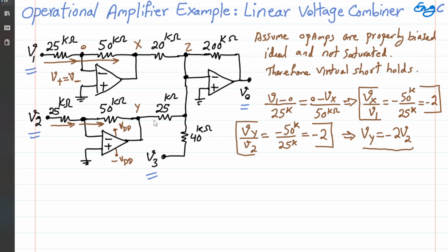So when we are computing, because we have 3 independent input voltages, when we say V1 like this, what we mean is effectively there is an independent voltage source connected to ground, and the value of it is V1. The same thing about V2. When we say we have V2 like this, it means there is an independent voltage source with a value V2 and then connected to ground. The same thing about V3. There is this independent voltage source connected to ground.